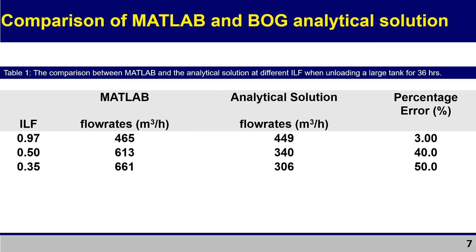at a high initial liquid filling, the percentage error is 3%, but as you decrease the initial liquid filling, the percentage error increases, and that's as a result of vapor thermal expansion that the analytical solution doesn't account for.